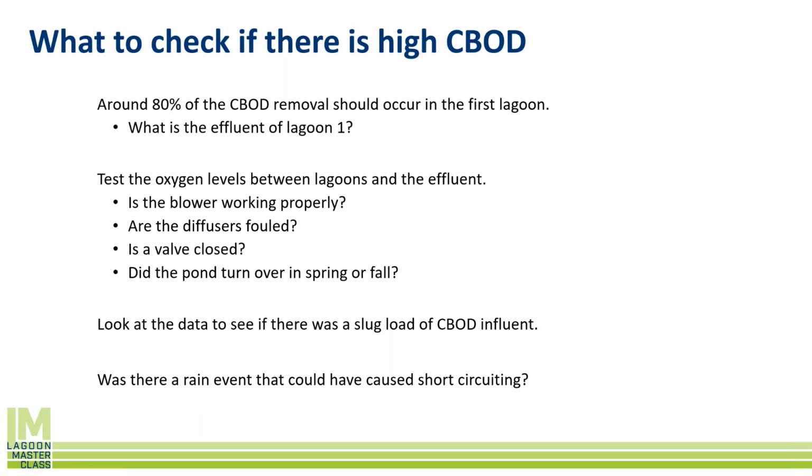So typically in most systems, the first lagoon will remove 80% of your CBOD. Now, that's a big generalization. In some systems it could be 70, in some systems it could be higher than 80. But when we look at the original design, we want to make sure that in the future, periodically we test after our first lagoon to make sure that the first lagoon is actually doing what it's supposed to do. That way we know what's going downstream is actually going to be at the proper concentrations where the downstream lagoons can actually treat that water.